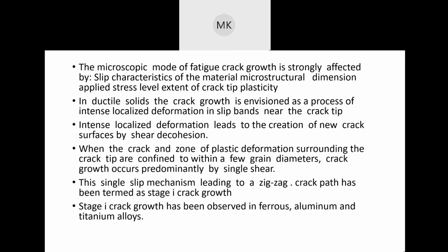That's the one in which you have all the dislocations, all the slip planes and persistent slip planes created in one dominant region or dominant crack, a dominant initial crack, and at that point is when you know that all the failure is going to happen in that plane of the material, but still the rate at which that crack is growing is slow.